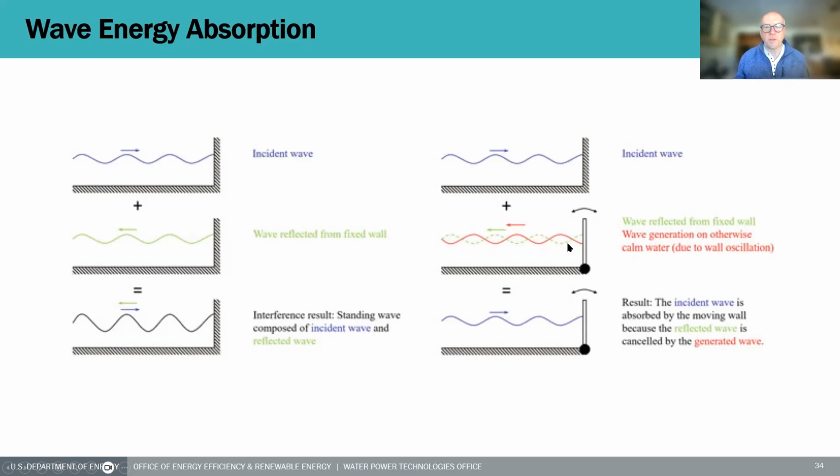And if we manage to cancel the reflected wave with the radiated wave, then there's nothing going out visually, and there's only the original incident wave coming in to this machine here on the right, to this pedal, and everything's gone. So the wave energy is fully absorbed. So that leads us to the often quoted saying that a wave maker is also a good wave absorber, or the other way around. So that's an important principle.